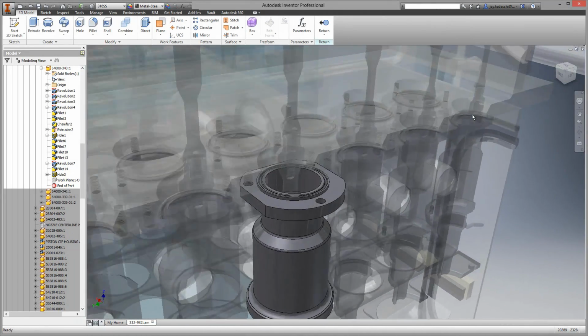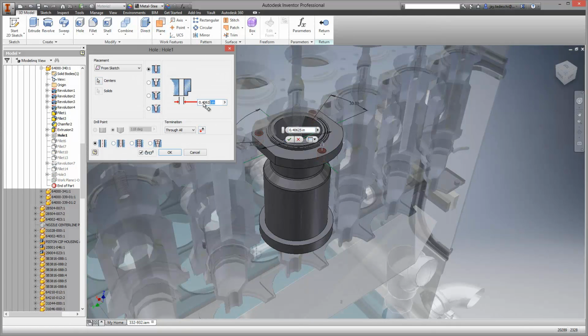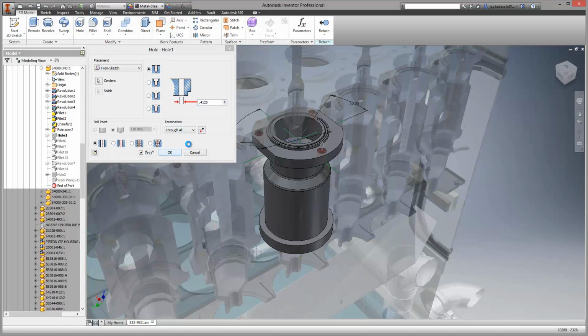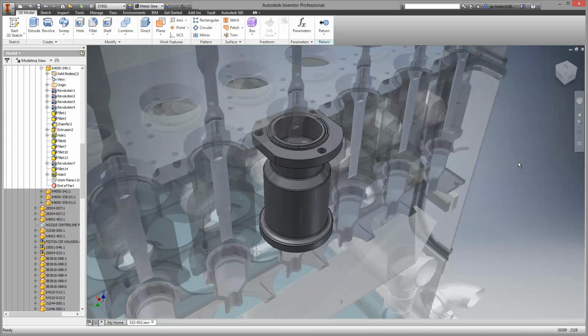So we've drilled down into this single component. We're now editing this component. Again, express mode. So let's pick the hole. We'll edit the hole itself. Let's just change the size of that. So update to the hole size. Again, I'm going to point it out, fourth time I've said it, still in express mode. So we edit the hole, and all of the holes on all of these same components update to the entire assembly. Now we'll go ahead and finish the assembly and then back out.